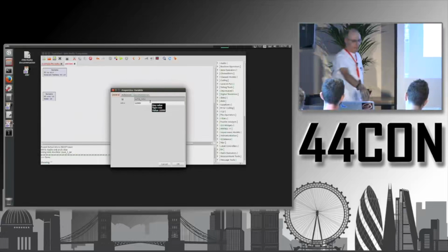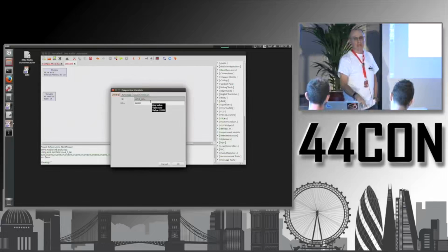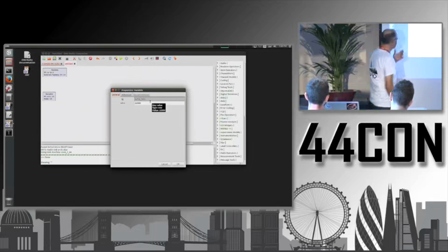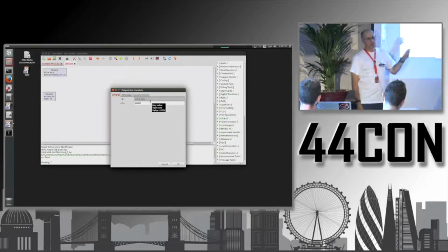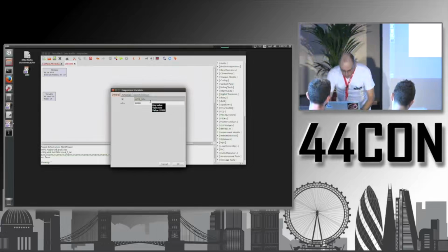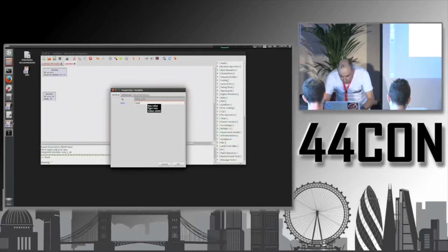Our device that we have here can go up to about 2 MHz as a sample rate. So we will use that, but we will not use exactly 2 million, we will use something closer by, and I will explain later why we do that. That's 1,920,000, like this.